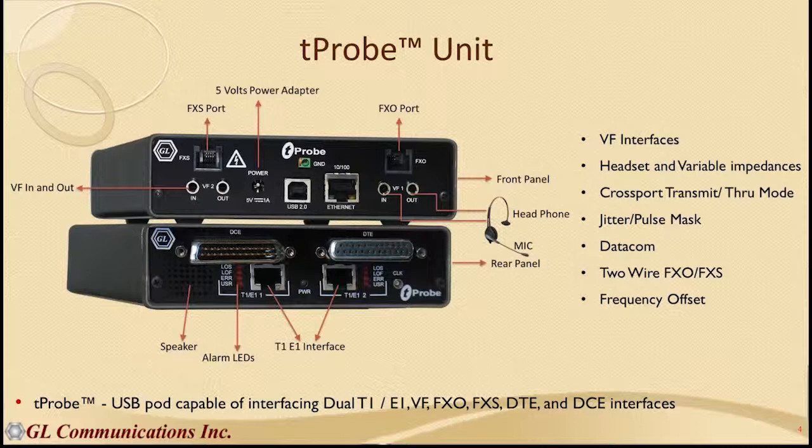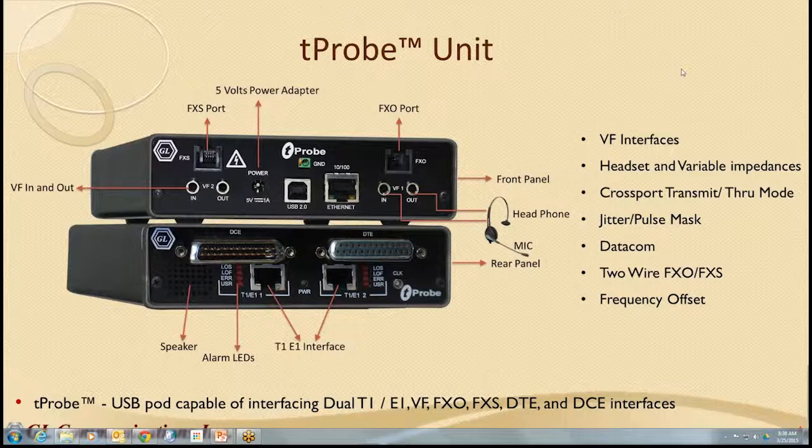Yeah, this is our tProbe analyzers, and this one has the ability to add optional boards such as Datacom Analyzer and FXO FXS simulation. These FXO FXS are used by analog phone lines. This FXO port allows you to simulate a two-wire FXO device such as a telephone or a fax machine.